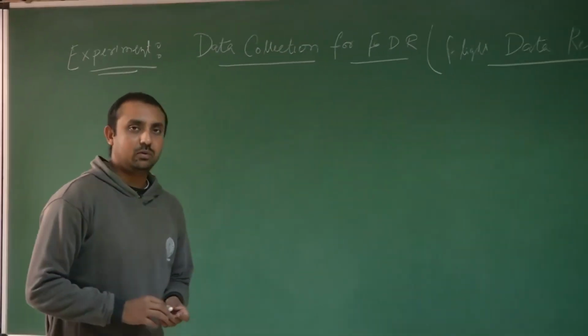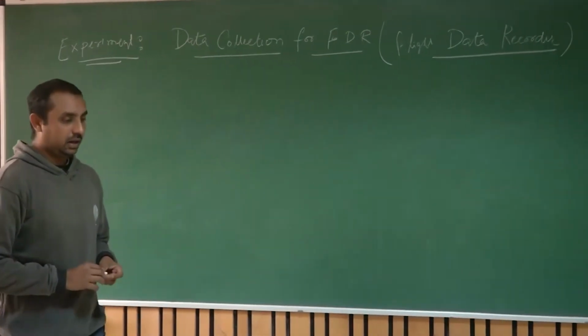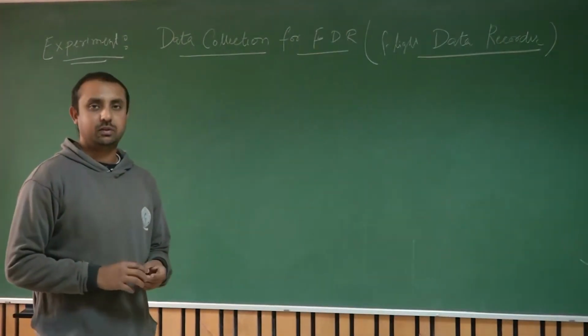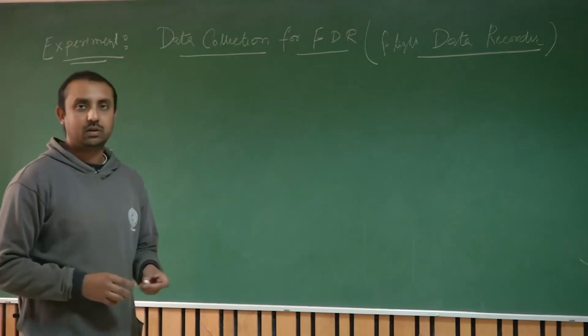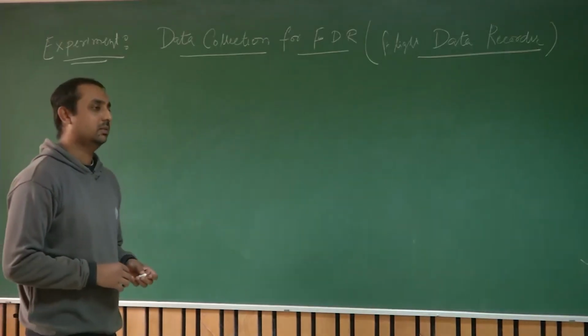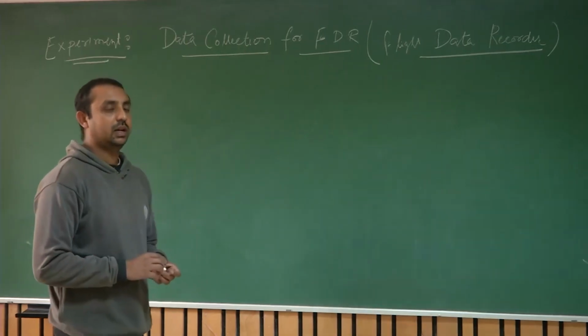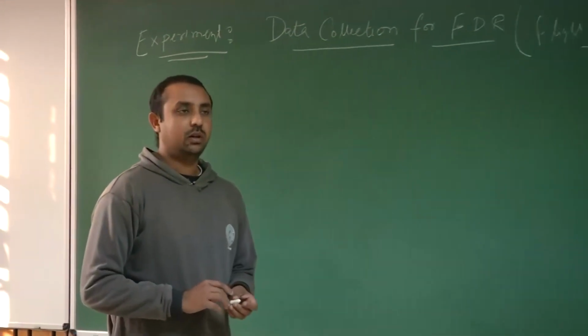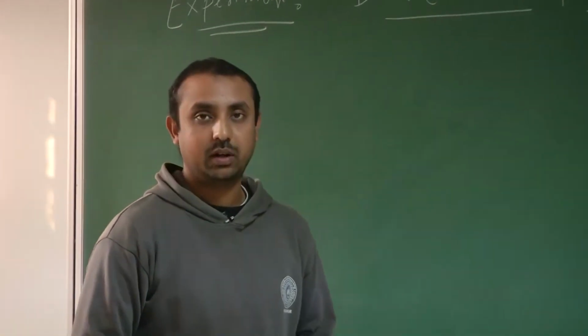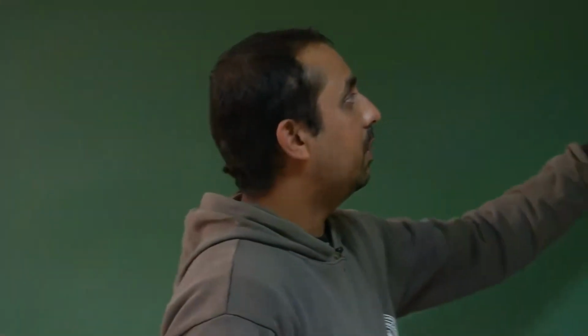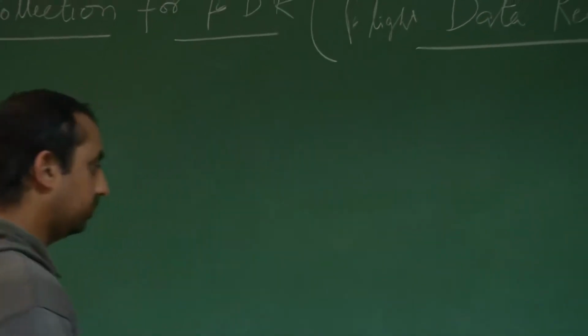In aircraft you might have seen while analyzing how the aircraft was behaving, you need to have data for different deflections as well as measurement of your angle of attack, side slip angle, also whatever the pitch rate, roll rate, yaw rate, and what were the value of thrust, everything is accumulated or combined in flight data recorder.